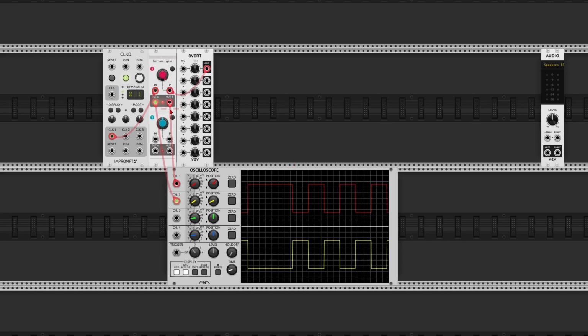on each incoming gate. And also in this mode, the CV input is combined in the same way with the probability knob. So setting this to -5 volts now will change the probability to 50%, and setting it to -10 volts will subtract this from the 10 volts currently on the probability knob, so it will never change. Now if we click this button again and reset everything, the module returns back to the standard mode, where each incoming gate is sent to either the A or the B output.